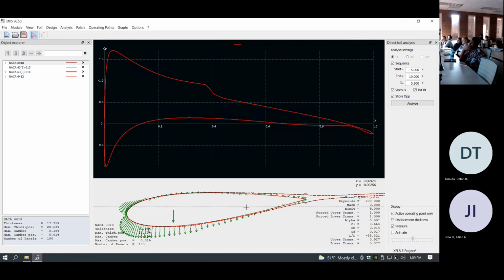So you have to fully close your airfoil to get proper results. You have to have a closed condition to have a real result. Yeah, that's right, because if you don't, your results won't be realistic and they'll be meaningless.